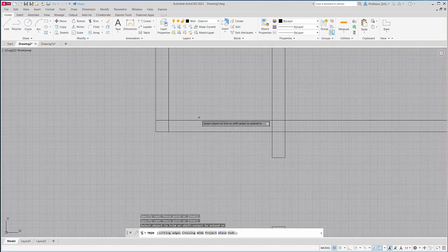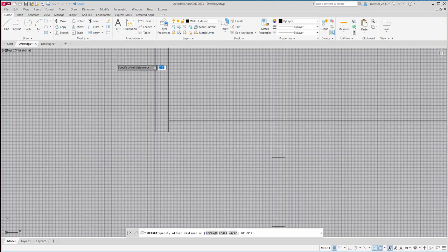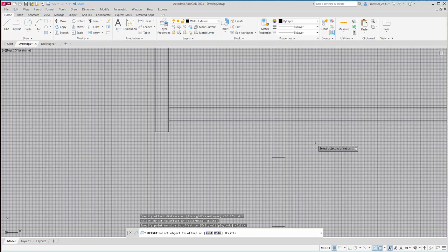Well, I've got an opening that goes backwards as well. So there's a 4-inch gap which I've already offset, so I don't need this line. Obviously, I don't need this one either, or this one. Good. I'll eventually have to get rid of that one anyway, so I might as well do it now. Good. Now I'm going to offset. How wide is that? 4.5 inches. 4.5. This line this way. Great.